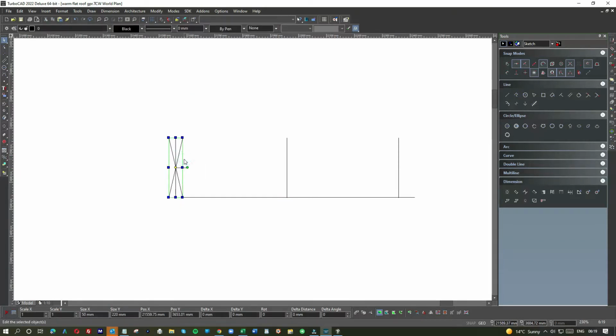What size is this? Probably it's 225, 220. It's about 8 or 9 inches. So the size or the height of this beam will depend on the roof span. In other words, the wider the roof, the higher this will be, the thicker the joist. So again, you have to be able to work that out. The engineer should be able to tell you anyway, but eventually you get good at working it out.